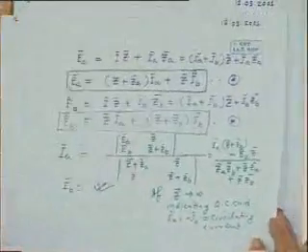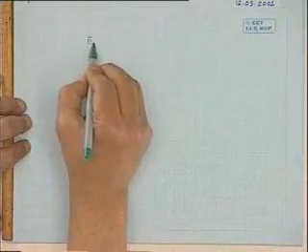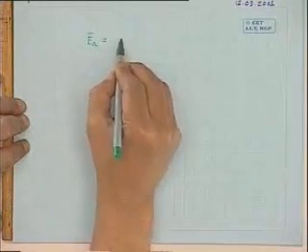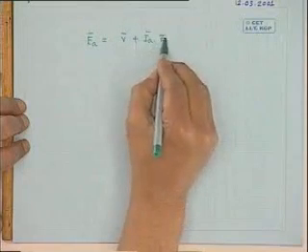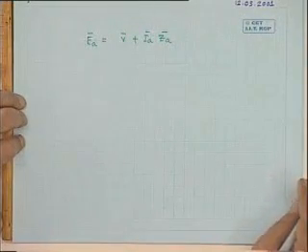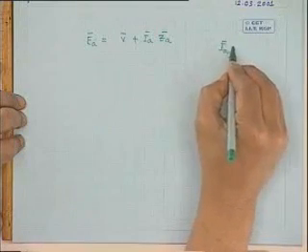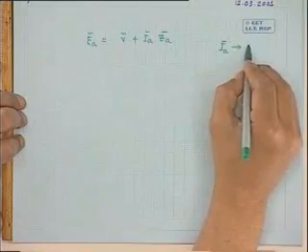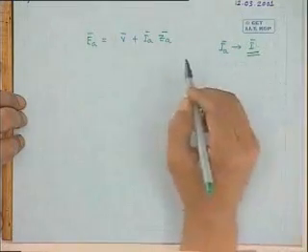Now, apart from this, I will do another thing which is slightly tricky in the algebraic manipulation. If you look at the first two equations, that is EA bar is equal to V bar plus IA bar ZA bar, that we have seen. It is sometimes useful to express IA bar in terms of the total load current I bar.